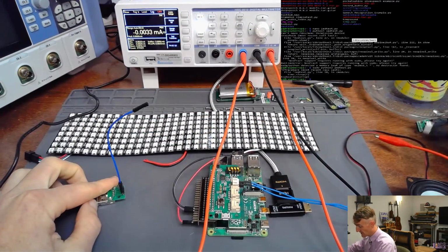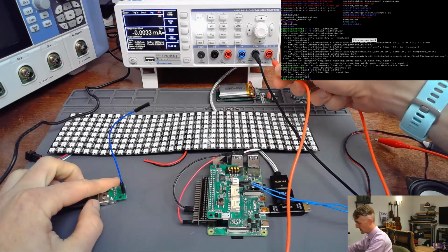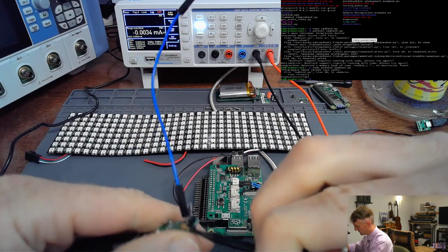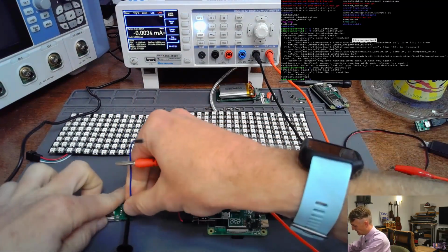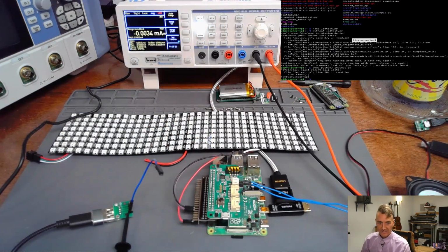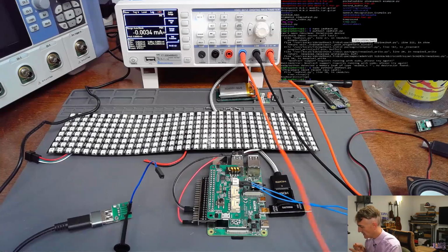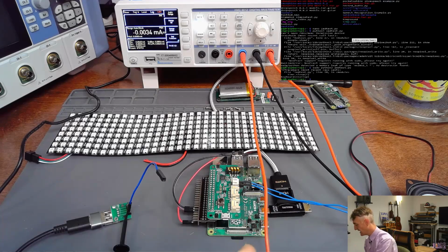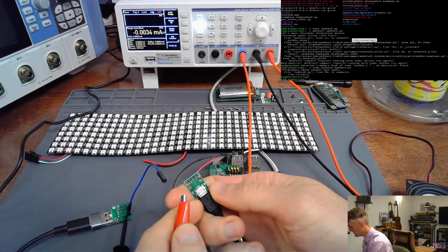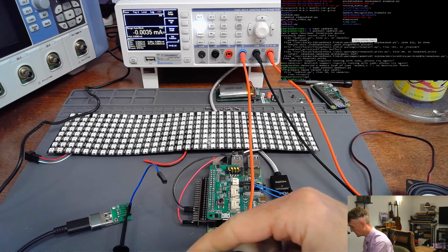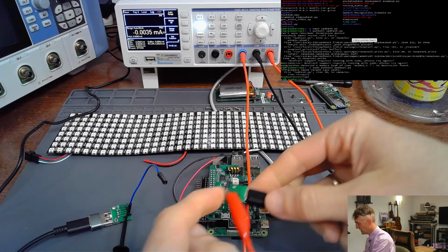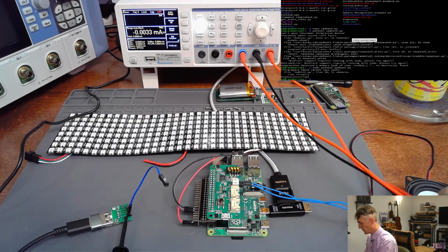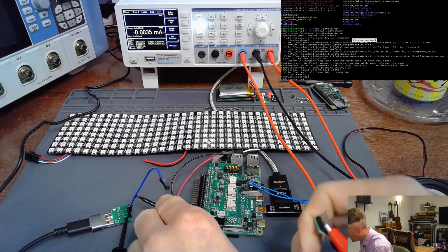and I do want to measure the voltage there. Actually, I need to use my J connector. So I want to measure the voltage here. Let's connect that. And I want to measure the current on the low side. So as it flows from ground, from the Raspberry Pi back, I have a whole bunch of headers over here. So ground, we'll put there. It will flow from here into the multimeter, out the black wire, and then back to ground on this side.